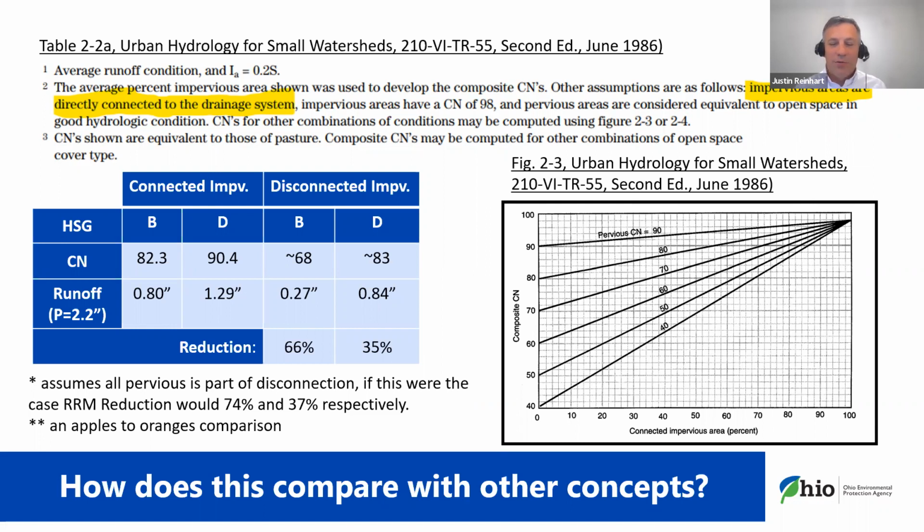And by oddity, I mean it's not a routable statistical sizing event based on risk tolerance that we generally do in our hydrologic engineering to size all of the rest of our stormwater infrastructure and our other development components. So what I've pulled up here is just information from TR 55, the USDA urban hydrology guidance. And many of you are familiar with that process through the curve number methodology to devise runoff peak rates and volumes.